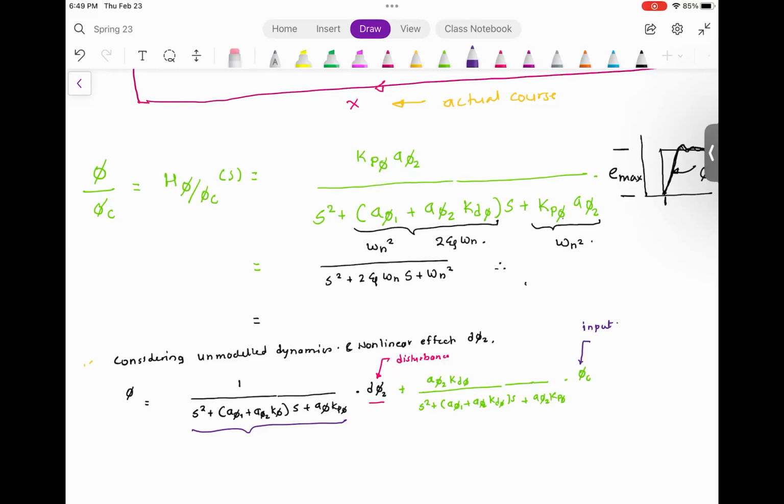But if you have a small steady state error, then what you can do is initially not turn the integrator on. As soon as the steady state error reaches beyond a certain threshold, you turn the integrator on. The integrator will take off the steady state error. As soon as the error all of a sudden increases, turn off the integrator, let the P and D terms do their job. And when you have a small steady state error, turn the integrator on. The integrator will take care of the steady state error. Everyone understood this?